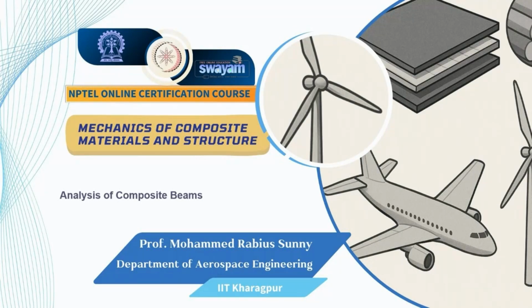So far the analysis of composites that we have done is for laminated plates, which are dominant in both the in-plane directions x and y. In the case of beams, it is dominant only in direction x, and accordingly the analysis is adjusted. This is how a beam is: its width is much less than its length, so the dimension along x is much higher than the dimension along y.